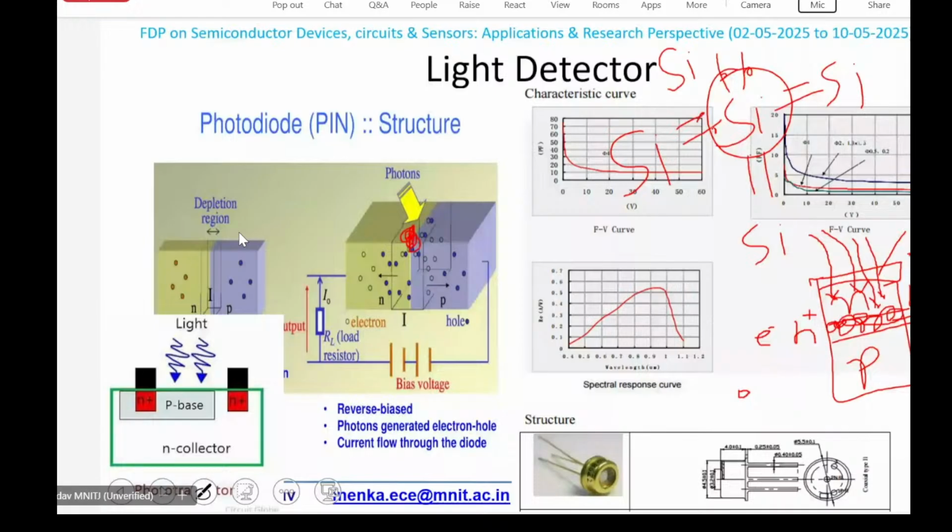As you increase the temperature, what is going to happen? The increase in temperature gives energy to the electrons in the covalent bonds, and these electrons get excited and come out of their state, leaving behind a hole, and the electron moves in the material space. So basically the electron hole pair is being generated, and this is called electron hole pair generation. And the reverse of this, when the electron is losing its energy and settling down into any of the covalent bonds, that is known as the